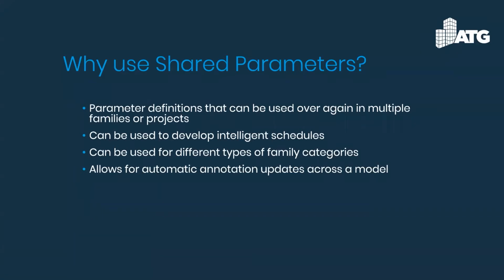Also, I've obviously seen a lot of companies still using Excel files within Revit, and that really is taking the eye out of the BIM when you do that. Obviously, I know there are some companies that have been accustomed to using Excel, and maybe it's something that's been used within AutoCAD over the years. But it's really time to drop that and start developing more of these intelligent schedules and utilizing the shared parameters.